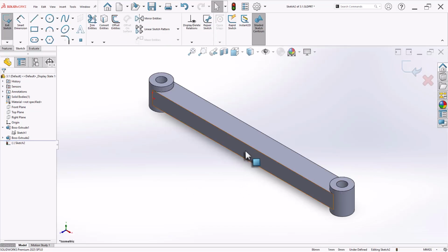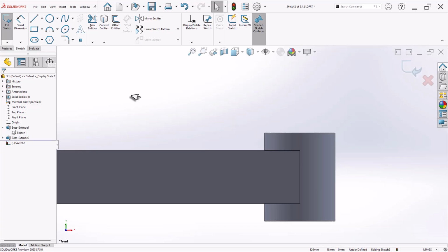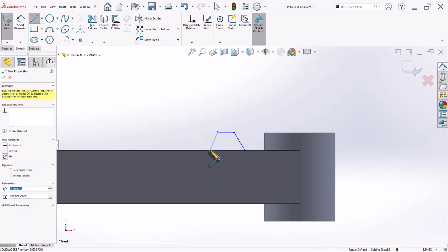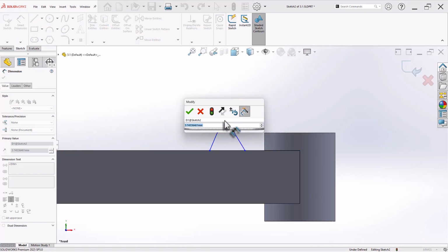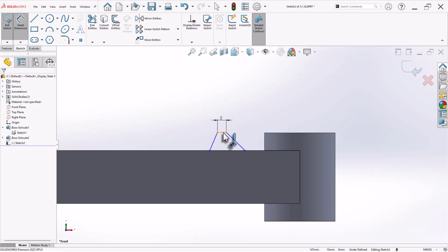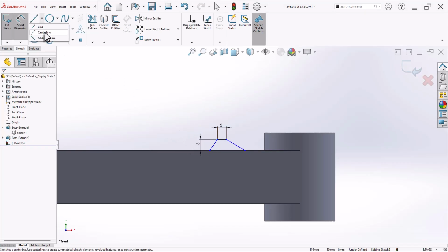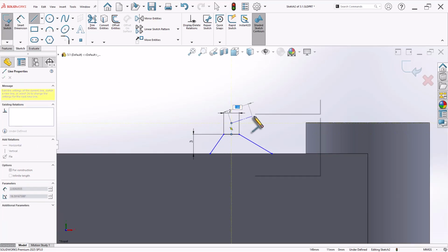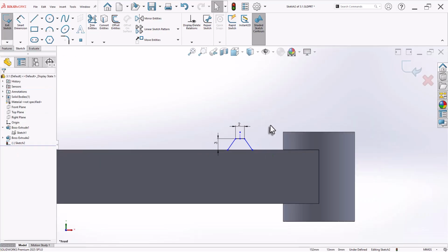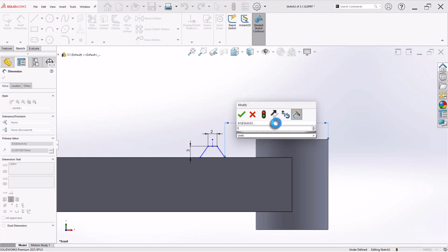the trapezoidal shape by creating sketch on this face. So let's add trapezoidal shape. This is 2. Height is 2.5. Now let's create center line and make these two edges symmetric. From here to here it is 18.